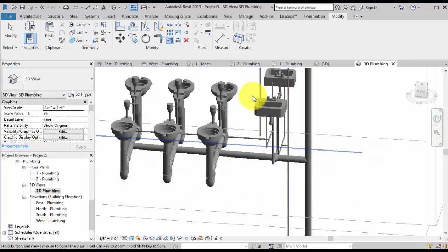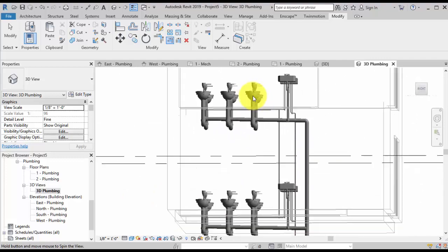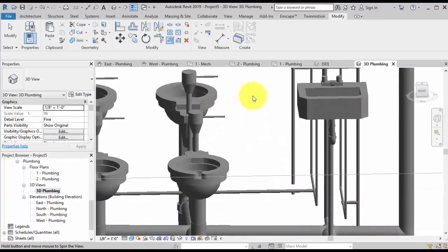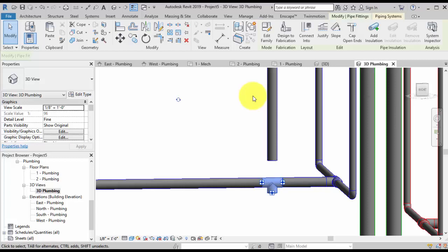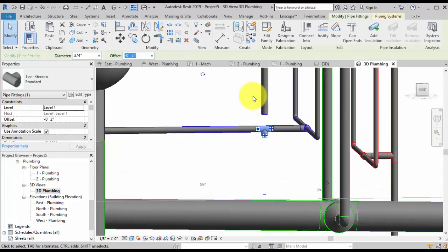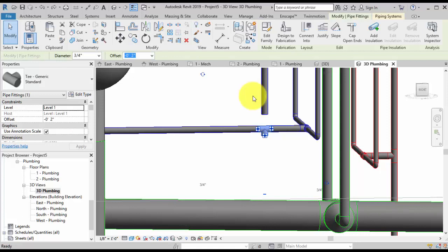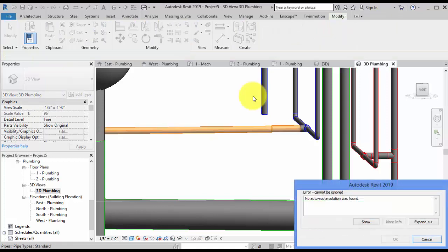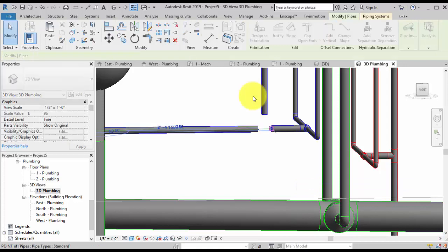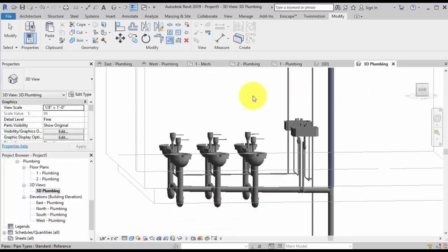So now the hot water will be all connected from the upstairs and downstairs, and the cold water too, because the cold water now is stopped right there. I'm going to select that and delete that. We're going to join that together, snap it right to it. It has some problem there, so we're just going to stretch. Okay, we're going to use the same extend feature and extend that, and then we join that, so the cold water is also all connected.